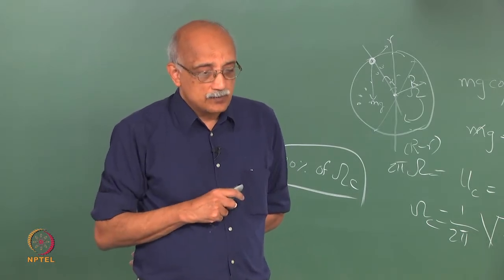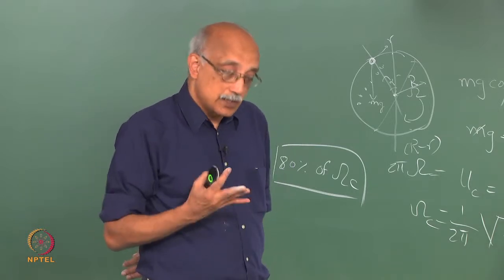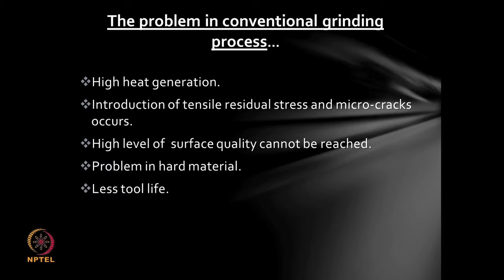In a ball mill, you can build in residual stress. One thing that does happen is the surface energy of a particle that exits a ball mill is much higher than the surface energy of a particle that enters the ball mill. So, maybe sometimes that is good for your process, but frequently it is not. And similarly, there is a lot of residual stress that can make itself manifested later on. Micro cracking can happen. You may introduce very fine defects into the particle that you may not be aware of when the process first happens, but which can later on come and affect your process.